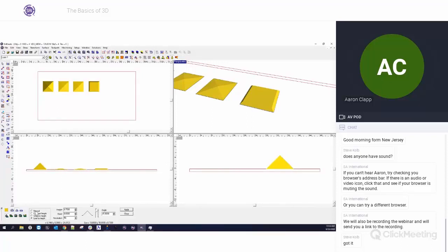Now, what's really nice about these different reliefs is that I can stack effects on top of each other. So for example, let's just say, I'm going to put this back to normal. I have my triangle right here, or this last relief selected, and I'm going to hit round relief. I'm just going to say add. And just like that, it now adds that existing effect on top of it. So you can combine and you can do different things to an object via adding or subtracting. So I can stack effects on top of each other if that helps me create something unique that I'm looking for in a particular letter.